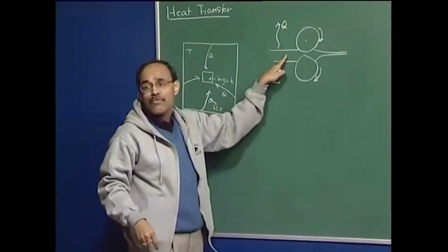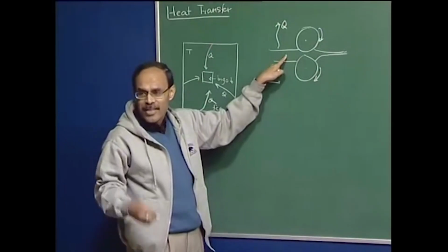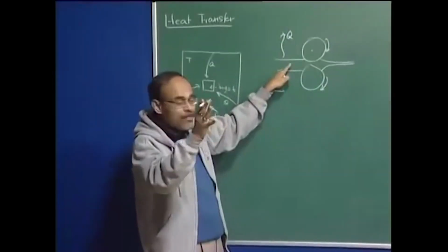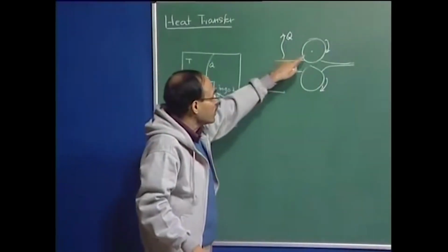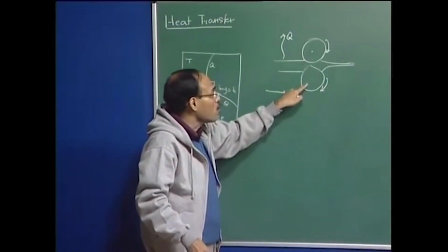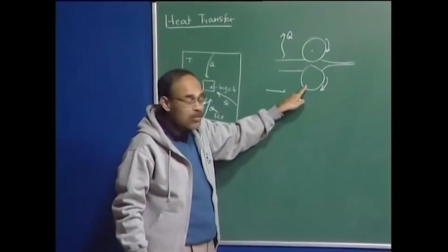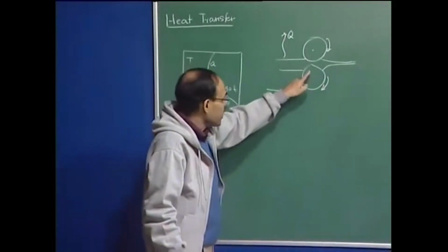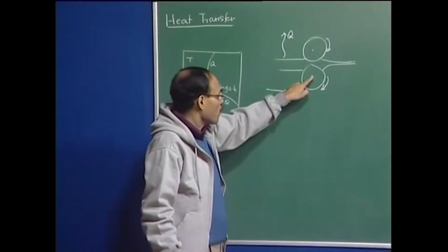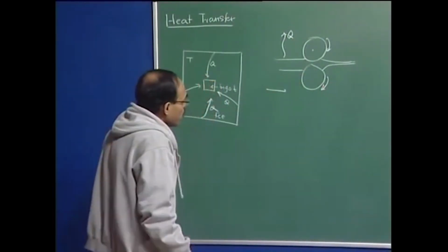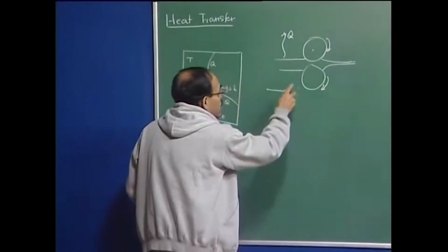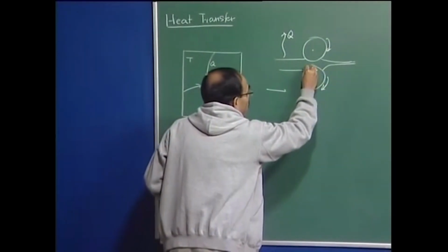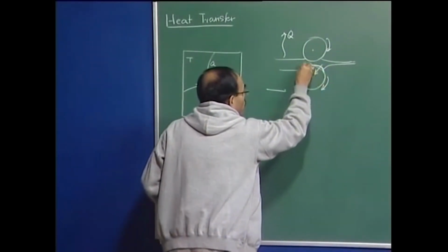Then there is heat evolution within the solid because of mechanical working, conversion of mechanical work to heat energy, where an efficiency factor is involved. And then because of the contact between the roll and the solid, and this roll is always water cooled to maintain a relatively low temperature, to maintain its low deformability, and to have good heat transfer rates, we have heat flow from the solid surface into the roll.